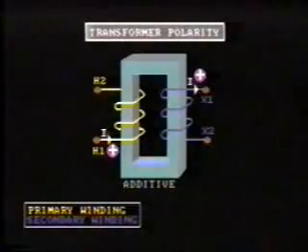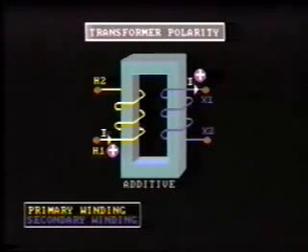In connecting up instrument transformers to relays, it's obvious that we have to pay particular attention to the direction of current flow, that is, polarity. In discussing polarity in an AC circuit, we are referring to instantaneous values of voltage and current. But what is meant by polarity?